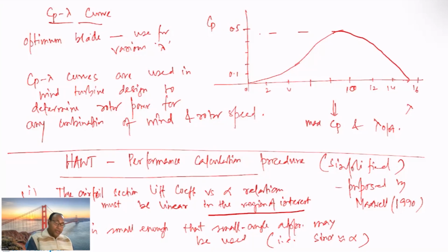So one can immediately, those who are familiar with the airfoil theory or airfoil aerodynamics, see that this clearly indicates this is applicable for the unstalled region.